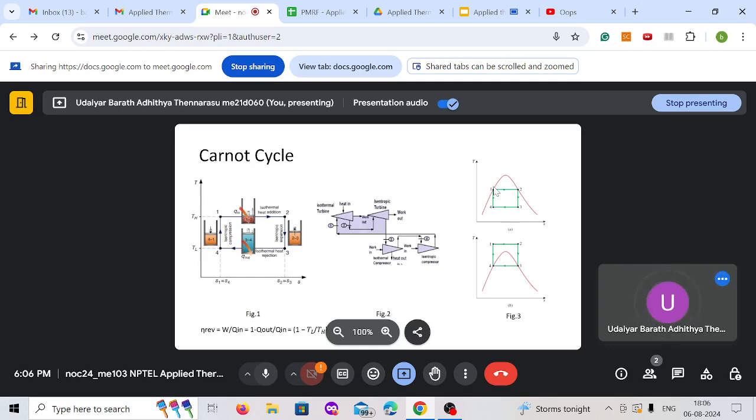So that requires you having a heat exchanger of very large, bigger sizes. So if that is what is required, so the process 1 to 2 and 2 phase dome, your heat exchanger size is very large for delta T too small. But physically speaking, having a large heat exchanger size means you have a large pressure drop. So there is a problem there. So these are all the problems which happen when physically constructing a Carnot cycle.